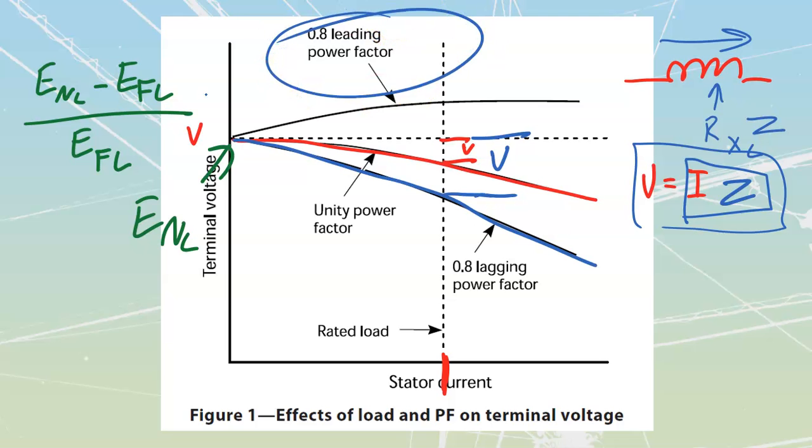We talked about how they raise the voltages on transformers. They also raise the voltage on alternators or generators themselves, and this is a dangerous thing because if we put too much voltage to stuff, we let the magic smoke out of those components. So what we see off of this one is that now we have a rise that happens before we ever leave that machine. It's going to add on to our value of voltage.